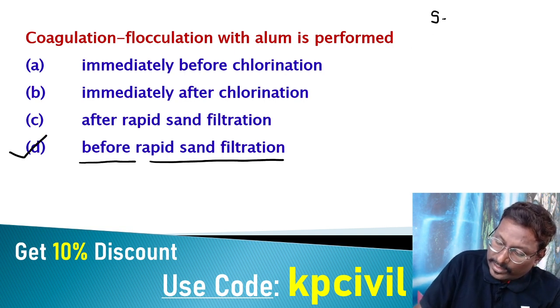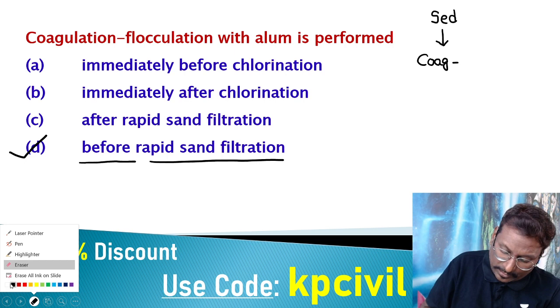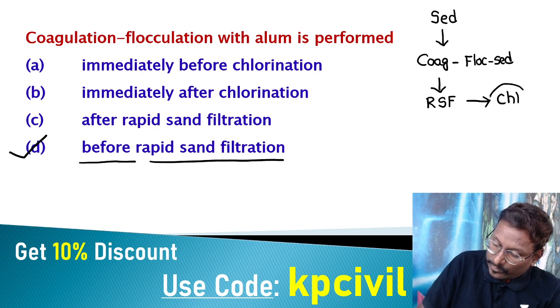First we are doing sedimentation. Then we are doing coagulation, flocculation, sedimentation. After that, rapid sand filtration, followed by chlorination.